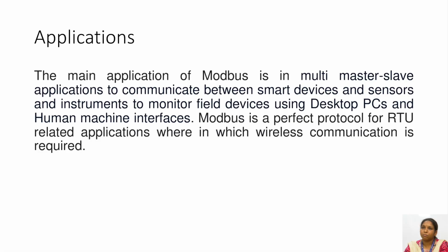The applications of Modbus. Modbus is used in multi-master slave applications to communicate between smart devices, sensors and instruments, to monitor field devices using a desktop PC and a human machine interface. Modbus is a perfect protocol for RTU related applications in which wireless communication is required.